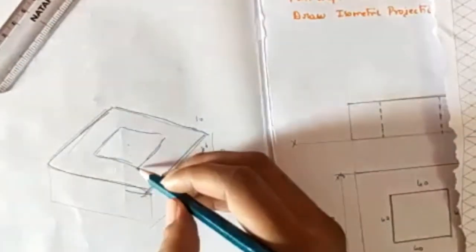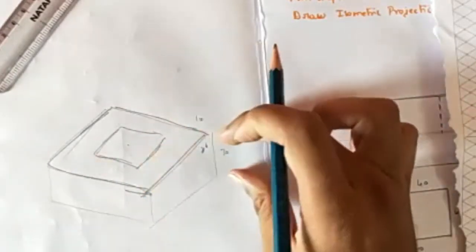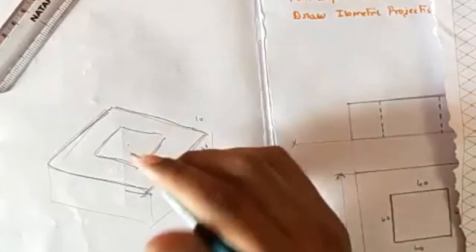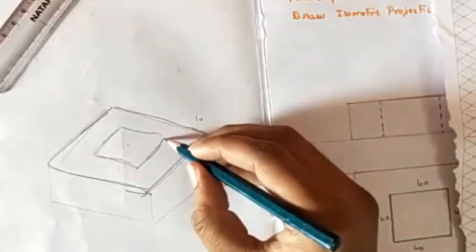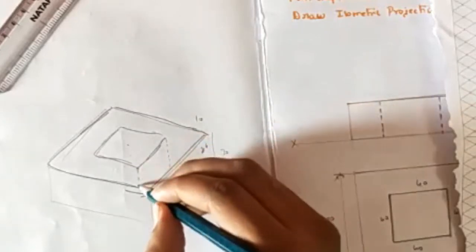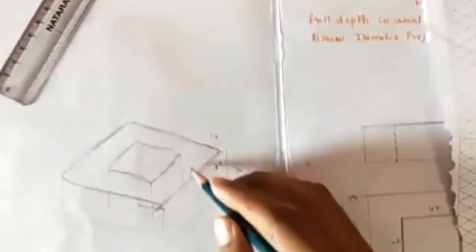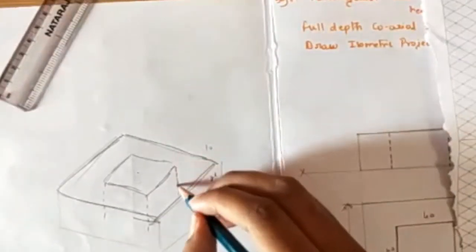So it should be a through hole. How does a through hole look like? That means this portion has to be cut inside. What is the total thickness of this slab? It is 30. What I'll be doing is, look at this. I'll be dropping 3 boxes below from all the 4 corners. Can you see the dotted lines? I'll be dropping 3 boxes down because the total thickness is 30.